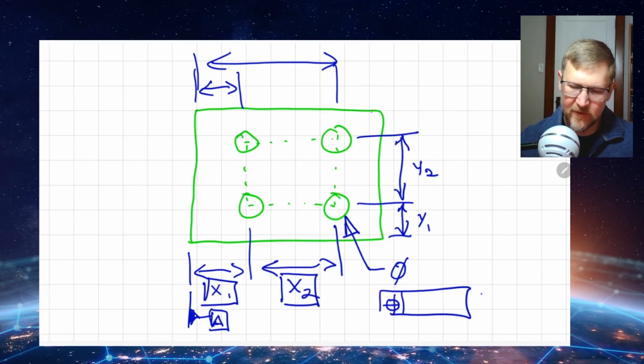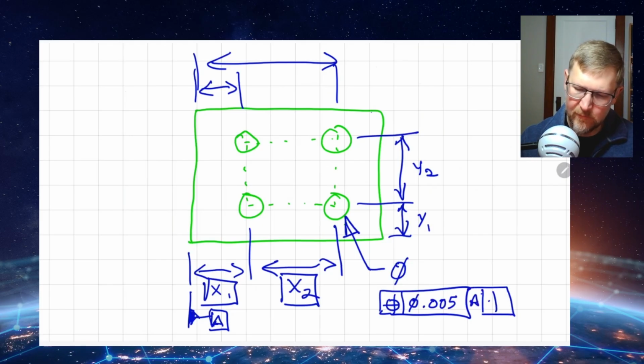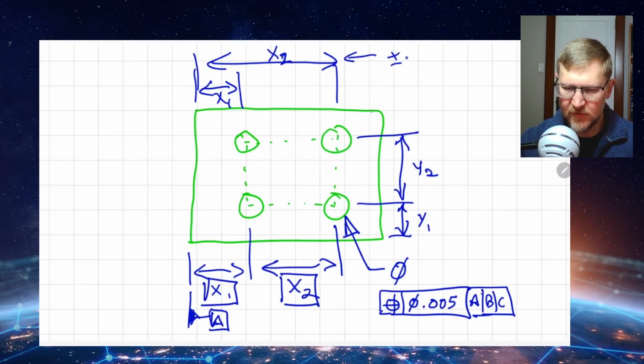And so this position tolerance is going to be a little bit different than the linear dimensions. Typically it's some sort of diameter, and it might be, for example, 5/1000ths of an inch. So we'll talk here in a second about what that is. You'll usually have some additional datums that this is referencing, but if I went with the basic dimensioning technique, and let's just say I'm going to put x1 here, x2 up here. If I was using this technique where I was measuring these linear dimensions, they're typically going to have some sort of plus or minus dimension to it.